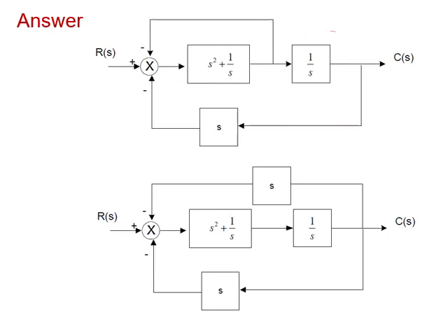What is the other solution? He said take this one inside. How to take this one inside? What's the meaning of taking this one inside? If you look at it carefully, you are going to find that here we have a pick-off point with input and output, another output. So I want to send the block from the output of the pick-off point to the input of the pick-off point. What is the rule? The rule is saying if you move a block from the output of a pick-off point to the input, the other output is supposed to take the reciprocal, meaning 1 over the value.